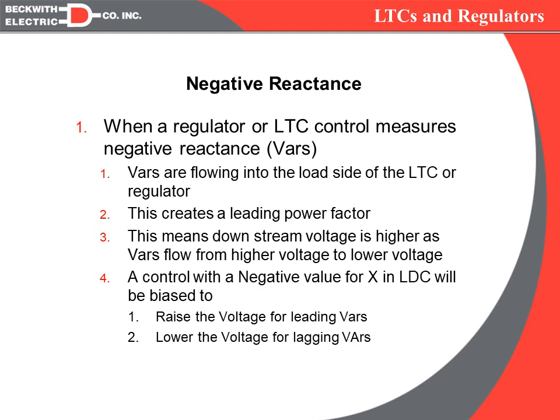They're all going to be looking at voltage, but the time delays will be set so that the capacitor banks are always shorter than the regulators and the LTCs. So that if a voltage needs to be raised or lowered, the capacitor banks will always be the first to operate. Now, if the voltage needs to be raised and we get too many capacitor banks closing and we go too far leading, then we're going to have the negative X in the line drop force the regulator or the LTC to raise the voltage to induce one or two of the capacitor banks to come off so that we get back to closer to a unity power factor.